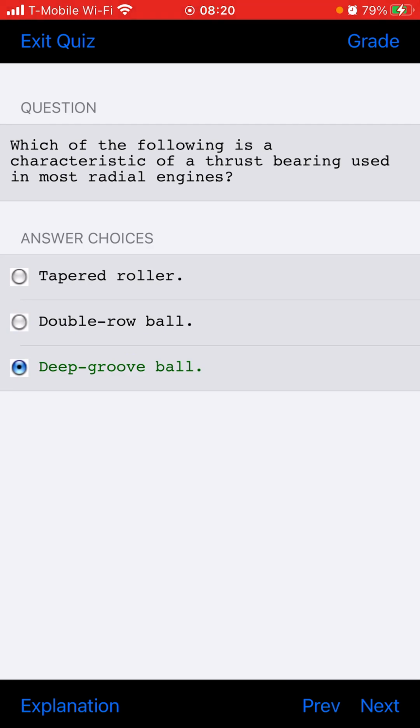What may be the result of incorrect installation of piston rings? Excessive oil consumption. What procedure should be followed when valve blow-by is indicated by a hissing sound on a reciprocating engine when pulling the propeller through? Perform a cylinder compression test to identify the faulty cylinders.